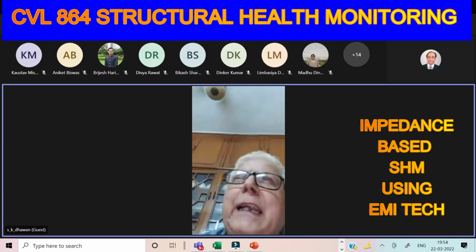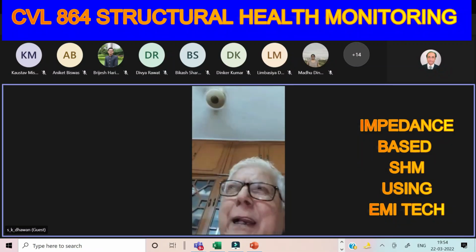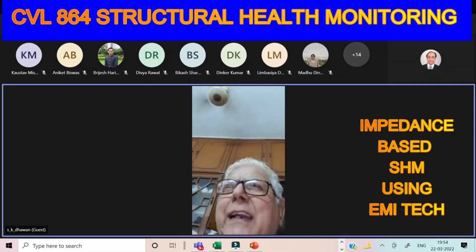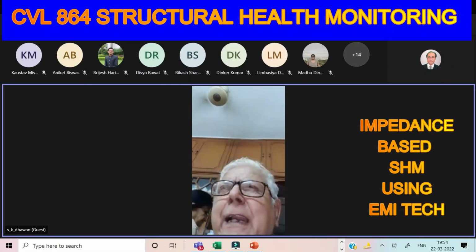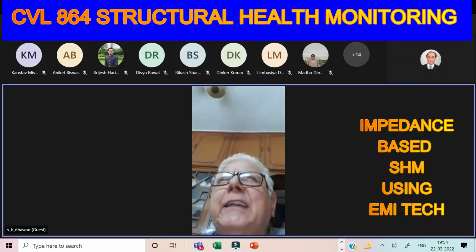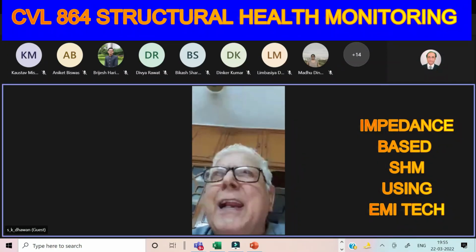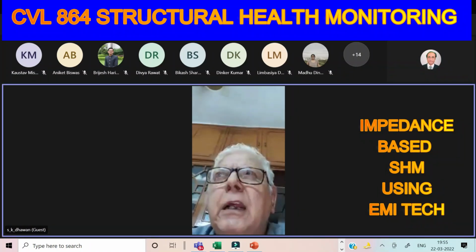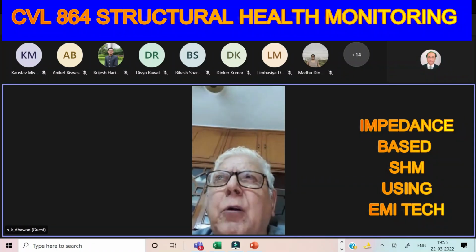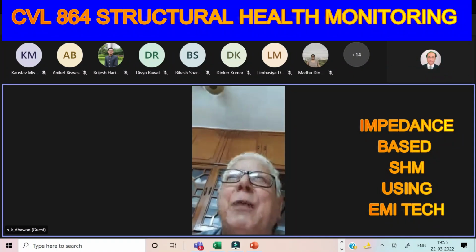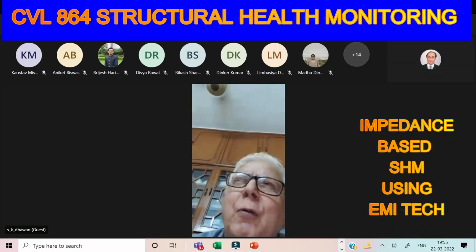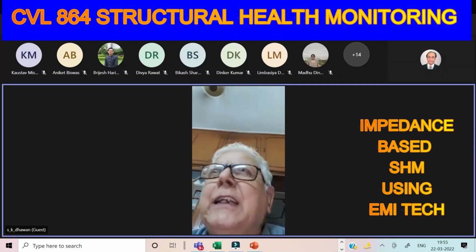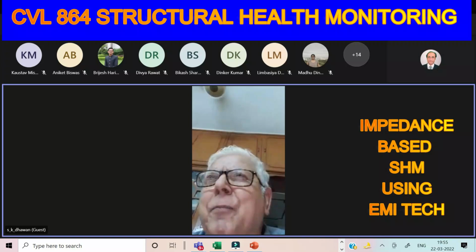Through the EMI technique, whatever Professor Bala said, I got the value of Z to X and Y with respect to frequency, then checked whether the system is parallel or in series based on what he has explained. So I did an actual experiment where I used this value, converted it to X and Y values. From X and Y values, I worked out the C, K, and M values.